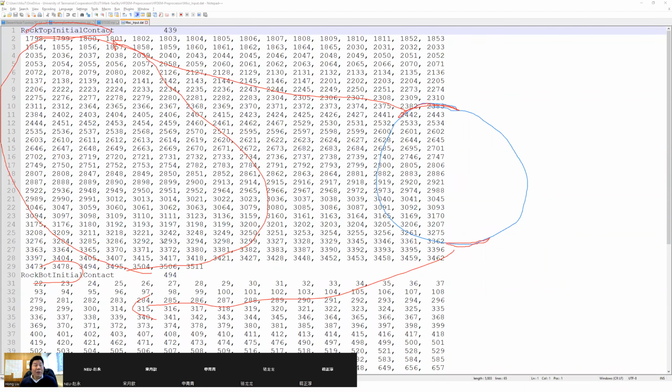And if you are familiar with Abaqus, you will notice that this data is very structured. Each line will have 16 numbers. After 16 numbers, it starts the next line. Okay, then for our case, what we need is, okay, this one, you can give any keywords, convenient for you to remember and understand that.